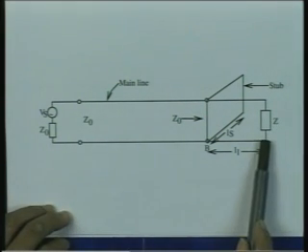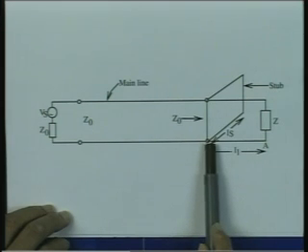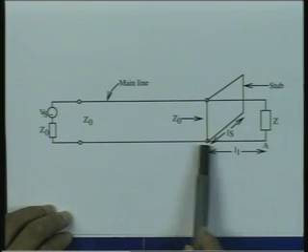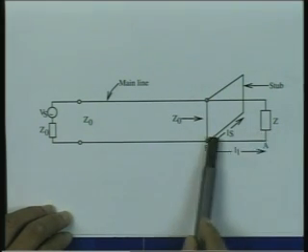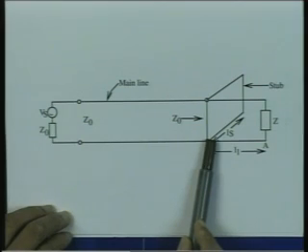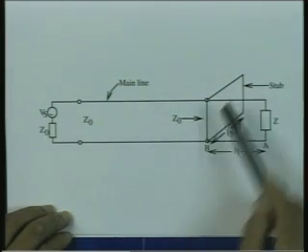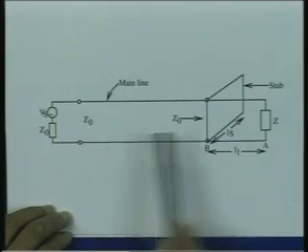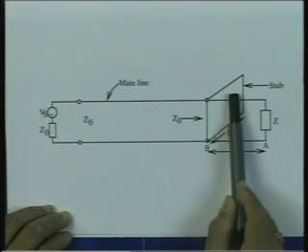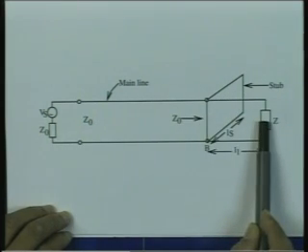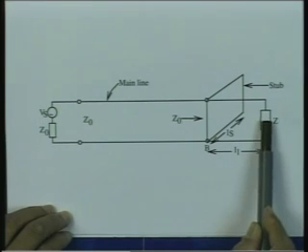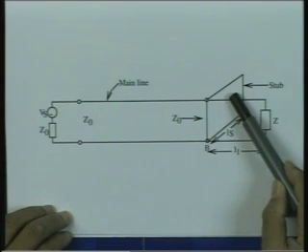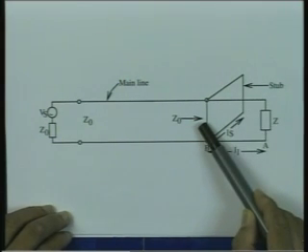So now the idea is that in this section here you have the standing waves because of the reflection from Z. The impedance is transformed from this point to this point, so you get a reflected signal which comes from here. The reflected signal is going to come from here also because this is short circuited. So let us see first how the energy will start flowing. The voltage wave comes here, it has two paths, one towards this stub, one towards the load. The voltage wave reaches the load, part of the energy gets reflected from here, so you have a reflected wave from here. The voltage wave which has gone toward the short circuit of the stub is fully reflected.